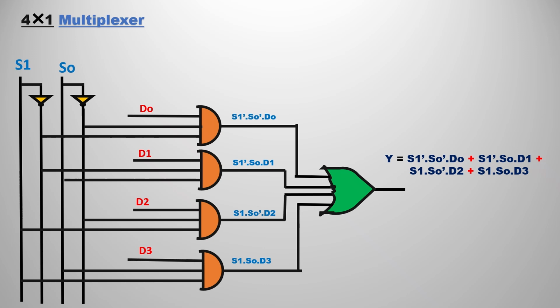Like that you have to pass all the inputs, and we have two select lines, that is s1 and s0. So in the output expression we have also the inversions, that is s0 bar. For that I am going to take the variables, the reverse ones, that is s0 bar, s1 bar. With the help of the output expression we can simply join and we can have the output expression. So this is the circuit diagram for the 4 cross 1 multiplexer.